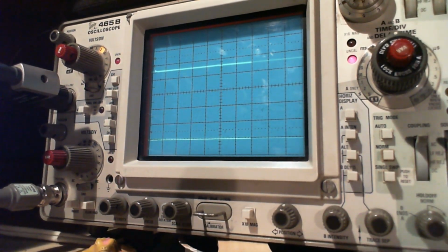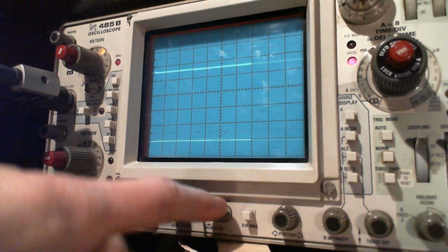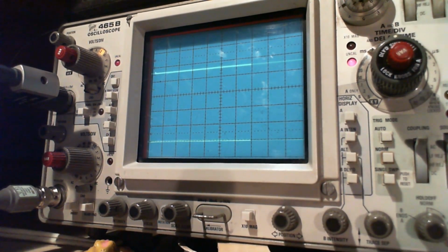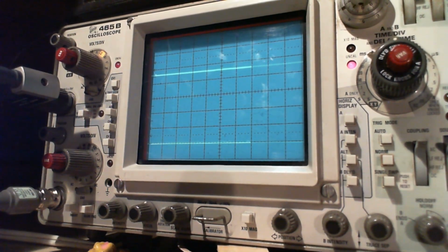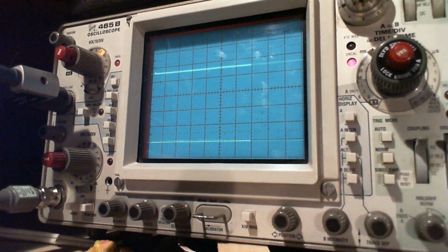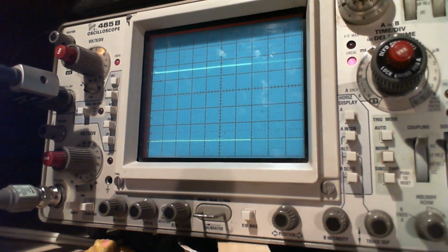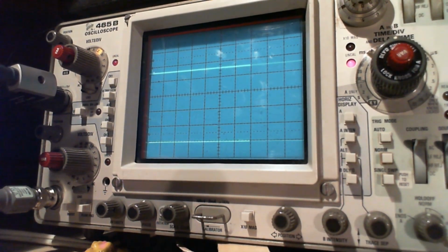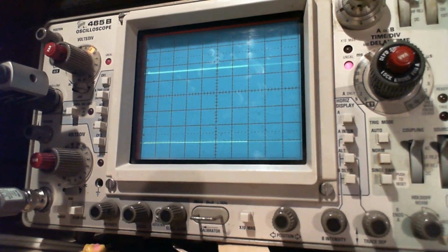So another option I have is to use the calibration voltage here on the other scope. You know which one to believe. Do I have another way of checking this? Unfortunately, I can't just whip a voltmeter on these things. They're square waves, and the voltmeters are calibrated for sine waves. What to do?